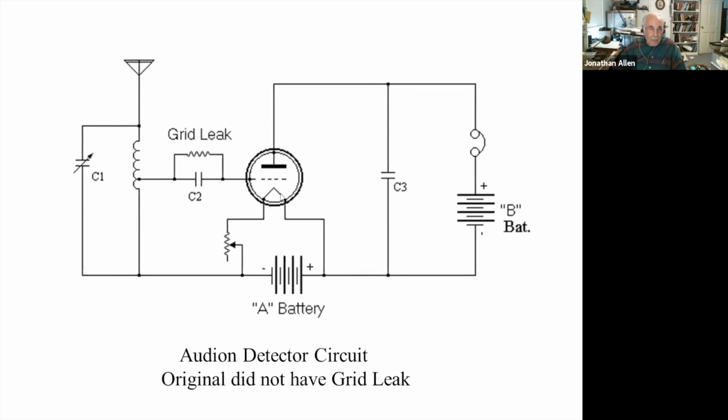Second problem is that he did not have this grid leak resistor, and hence there was no DC path off the filament. So the filament could float to whatever voltage it felt like as a result of electrons striking it or falling or getting knocked off it. And so the tube didn't know where in its operating curve it was happy. The geometry was certainly less than optimum.